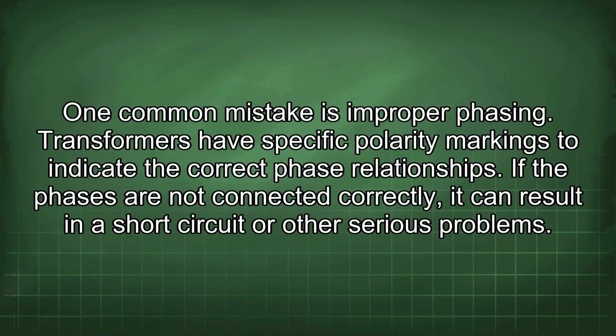One common mistake is improper phasing. Transformers have specific polarity markings to indicate the correct phase relationships. If the phases are not connected correctly, it can result in a short circuit or other serious problems.